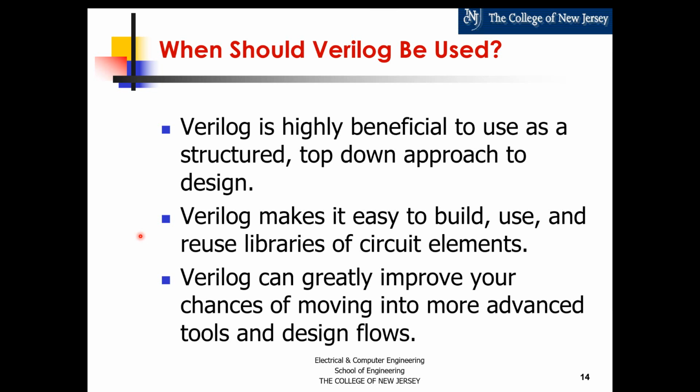And that way you can use what is called libraries of these well-known, proven modules or circuit elements. So that's how you should approach it, because you're not going to be developing libraries, which would be the bottoms-up approach. You're going to be assuming that things are there and then just traversing the hierarchy all the way to the leaf components.